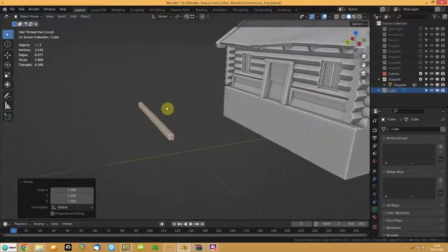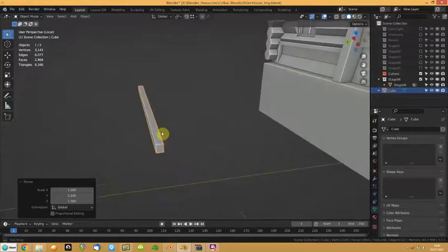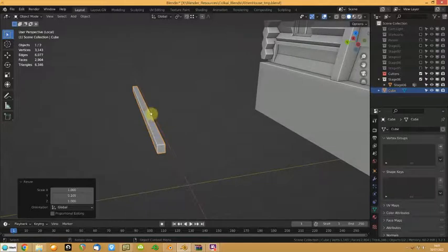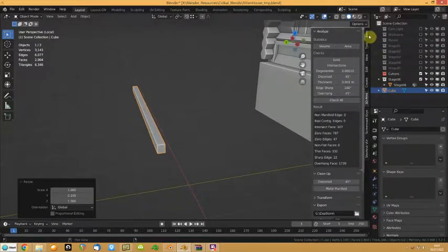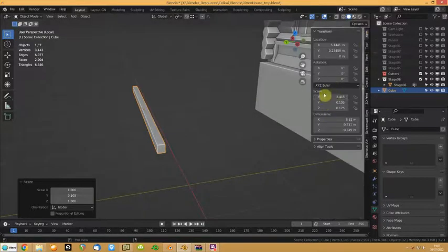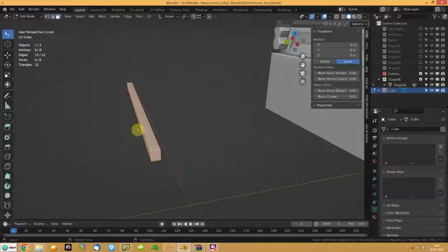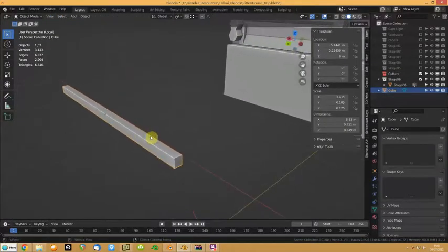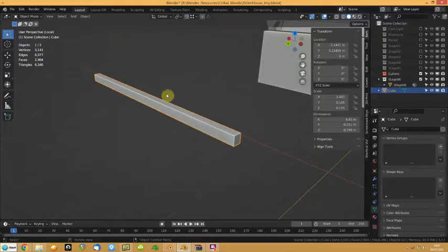Now, one thing I will just touch on before I finish actually is scale is important in Blender, if you don't already know. If I now try to go into edit mode and bevel one of those edges, Control B, it's not behaving as you expect it, and if I select that face and Control B, that is not what you think would happen. And the reason for that is it's still trying to apply that action on a one-to-one.